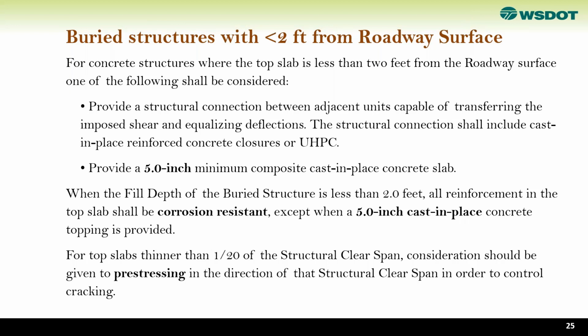We also have a lot of buried structures that are very shallow. When we have less than 2 feet from the roadway surface, in that case, provide a structural connection between the adjacent units capable of transferring imposed shear and equalizing the deflection. The structural connection shall also include cast-in-place concrete, or in some cases we use UHPC in order to have a more reliable and long-lasting connection between the precast units.